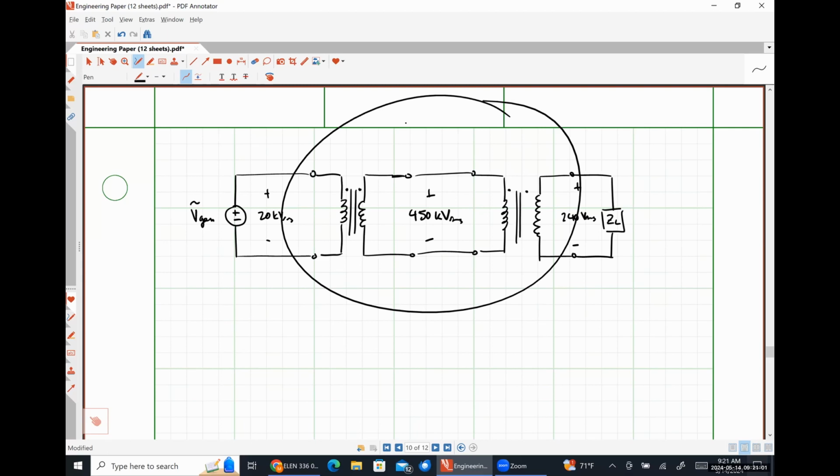because if you're getting 120 volts out of your generator, let's say your generator is rated for 2 kilowatts, which would be an extremely small generator, right? What's 2,000 divided by 120? 16, 18 amps, somewhere in that ballpark, right?